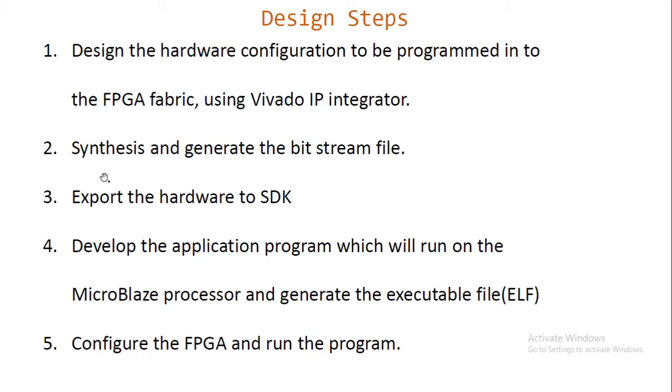In our demonstration, we will be mainly using a MicroBlaze processor, and to demonstrate the functionality, we will be using a simple UART for printing a message on the console. And other peripherals required for the MicroBlaze functionality will also be included using the Vivado IP integrator.